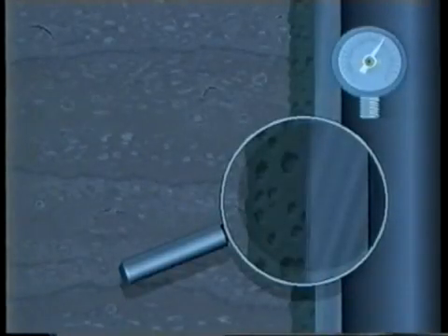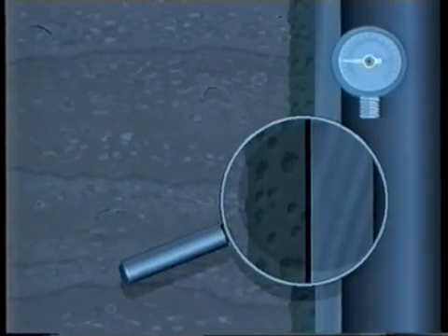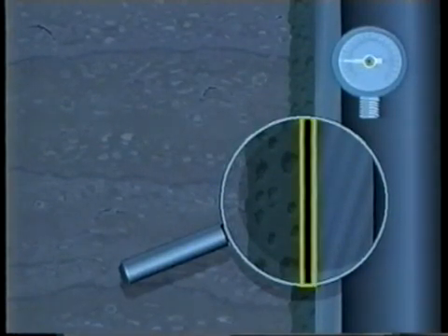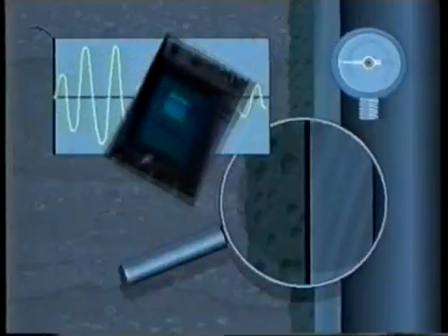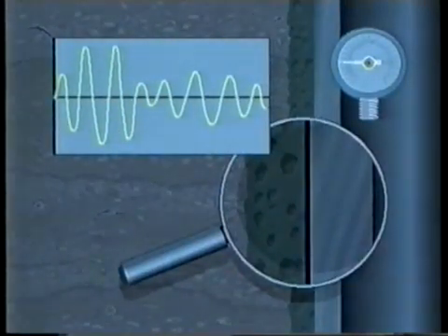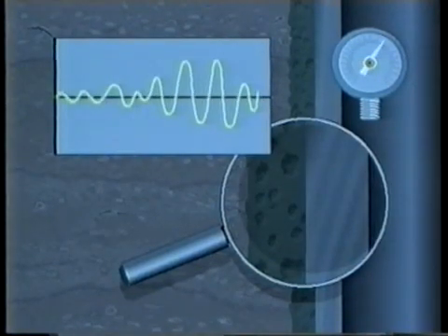A reduction in wellbore pressure from the time the cement hardens to the time of the CBL logging run can cause the pipe to shrink from the cement sheath, forming a microannulus around the casing. Even though this microannulus does not permit hydraulic communication, the cement cannot maintain the coupling to the pipe required to attenuate the acoustic signal. As a result, the recorded amplitude will indicate a poor bond. However, during logging, if the internal pipe pressure is increased above the curing pressure, the microannulus will be closed and an interpretable log will result.